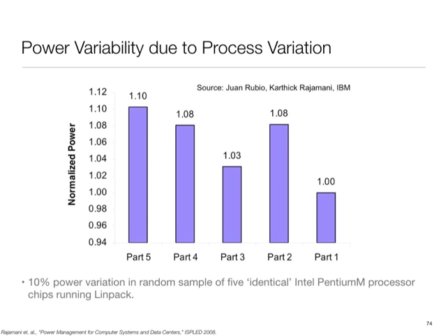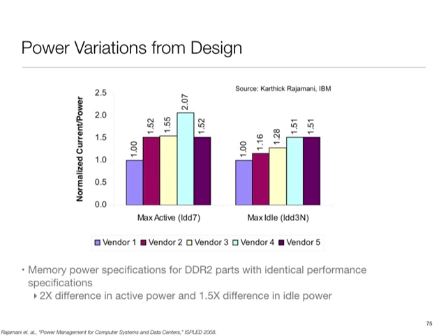So this is an example of variation in active mode power due to process variation. I'll show numbers later that the leakage mode power, the one consumed while the thing is idle, has even more variation. One of my former students did his PhD in this space, and a lot of his measurements showed that for ARM processors of around 3-4 years ago, you're talking not about 10%, but about 10x difference in leakage power consumption across nominally identical devices. I mean, different chips of the same design made on different wafers at different times. As I talked about, for designs which are low duty cycle, it's the sleep mode power which matters a lot, and if sleep mode power had that amount of variation, you can see significant variation in the system lifetime resulting from that. So something to be cognizant of.